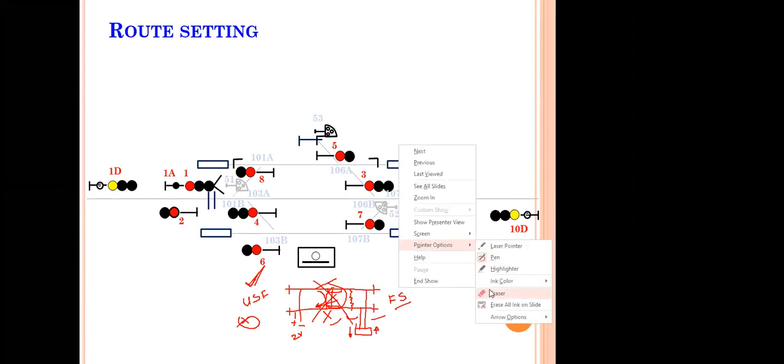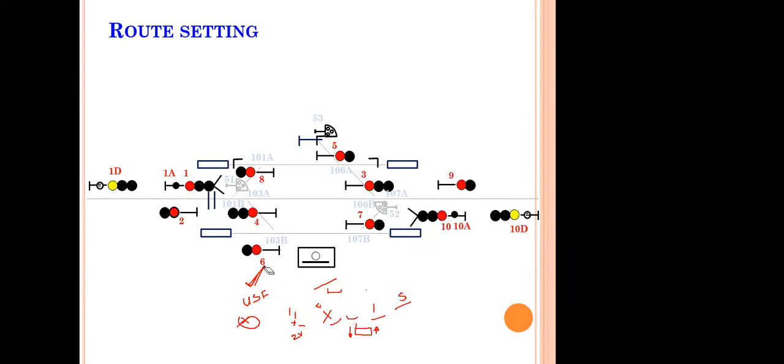That is better. Okay. So that is how the fail-safe works. Even though the conditions are prevailing to take off a signal, but still the signal has failed, no problem. No train will come. But if the conditions are not prevailing and I am taking off a signal, which is dangerous, that is unsafe side failure. The signaling systems are designed for fail-safe. They may fail, but it is on the safer side. No problem. The train will not come. Accidents will happen when the train rolls in. You prevent the train rolling in. That is how the fail-safe system is working. So as we discuss further, you will have more clarity.